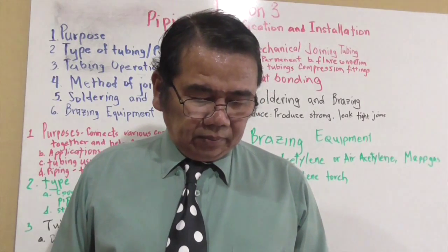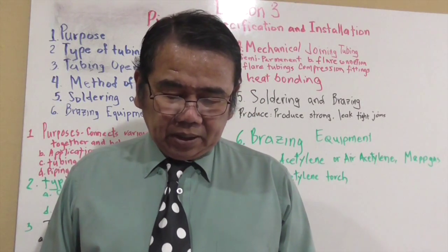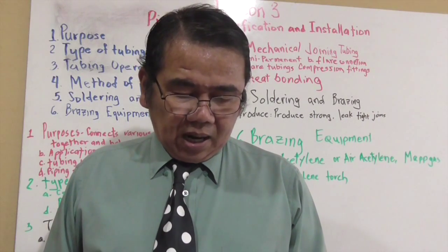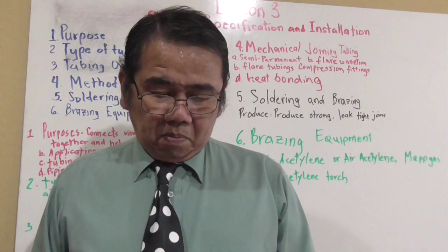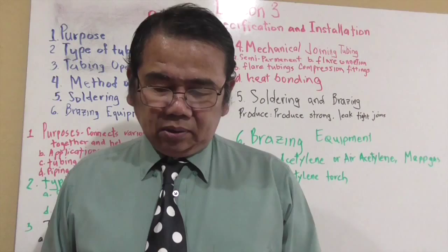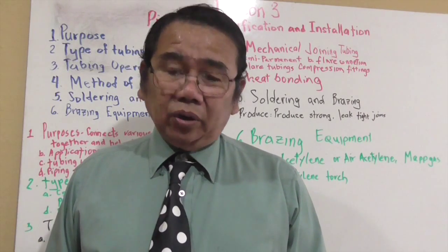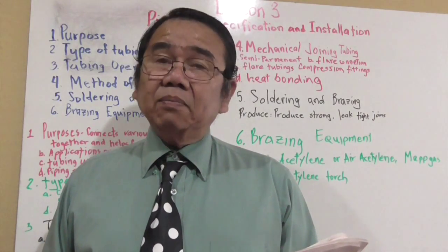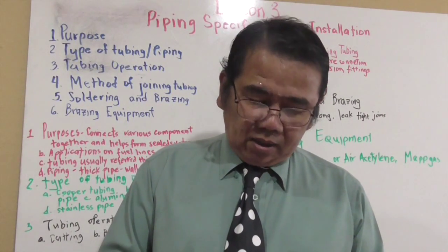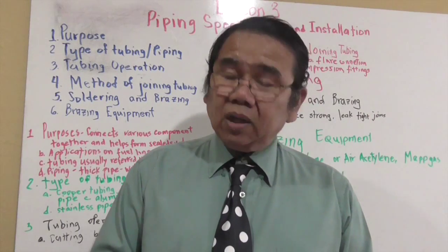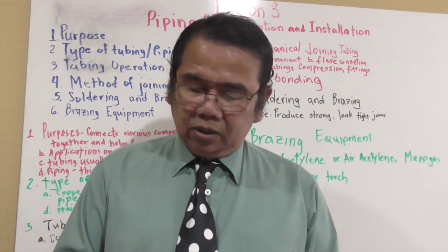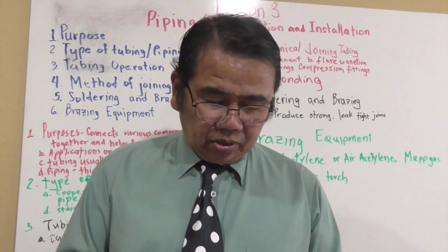Hard solder. The next one is hard solder. Brazing, high temperature silver solder. Hard solder joints make a strong bond. Hard solder is commonly called silver braze alloy, required by some building codes. Okay. Used in the air conditioning and refrigeration industry.